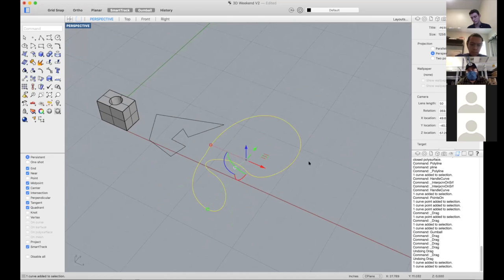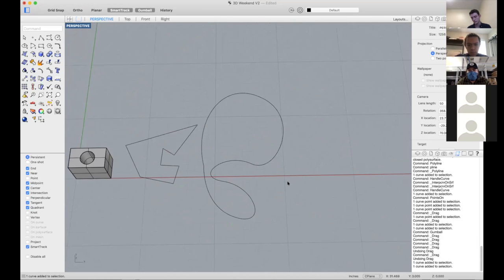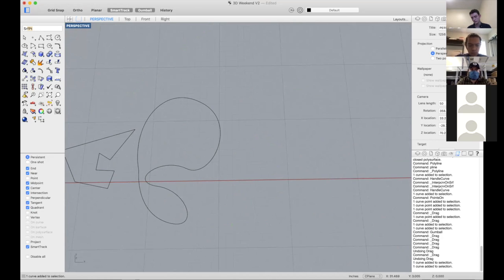So this is a curve. Your other option is a surface. The easiest way to make a surface is surface by point. A surface is always abbreviated as SRF. So any command that is a surface command is SRF and then something, except for extrude, which is backwards, so it's extrude SRF. That's just the way AutoCAD did it. So SRF PT makes a surface by point.